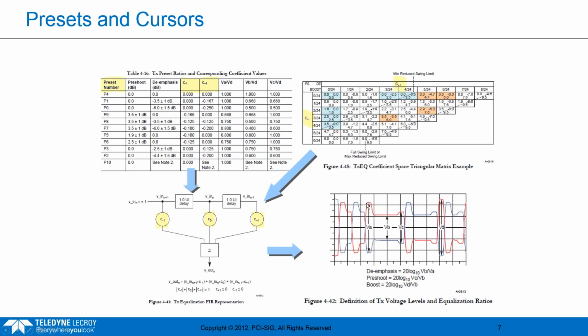So that's the bit right after the transition, and then we can see the subsequent bits are de-emphasized. So this is the de-emphasis. But there's also this VC over here, which is the pre-shoot. So this is the last bit before the transition. And so there's kind of another knob to tweak here, so it's a little bit more sophisticated TXEQ. It has the de-emphasis and pre-shoot values as well.